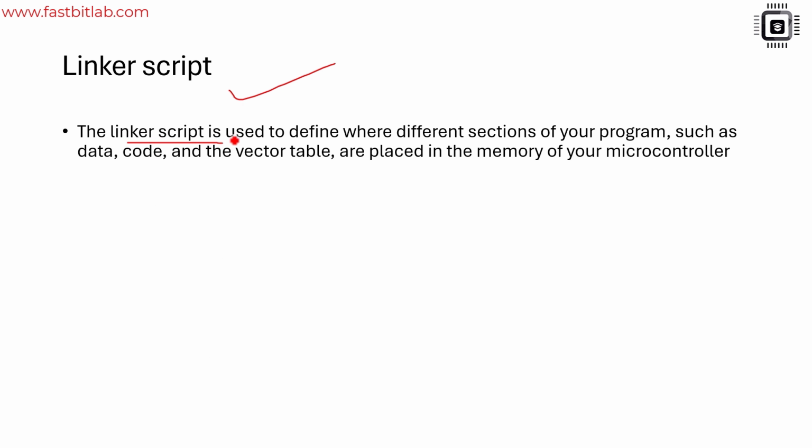The linker script file is used to define where different sections of your program, such as data, code, and the vector table, are placed in the memory of your microcontroller. And you can also use the linker script to customize stack and heap settings of your project.